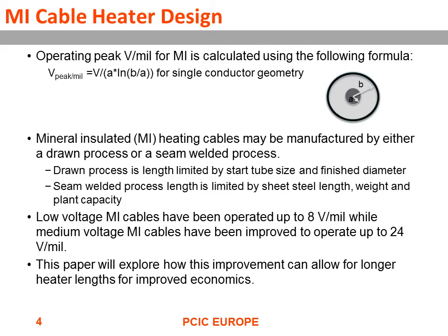One of them is high temperature, one of them is high voltage. The magnesium oxide is very NTC, negative temperature coefficient. As a consequence, as the temperature rises, the conductivity of the MgO increases many orders of magnitude from room temperature up to the 650 degrees C where we're operating the cable.